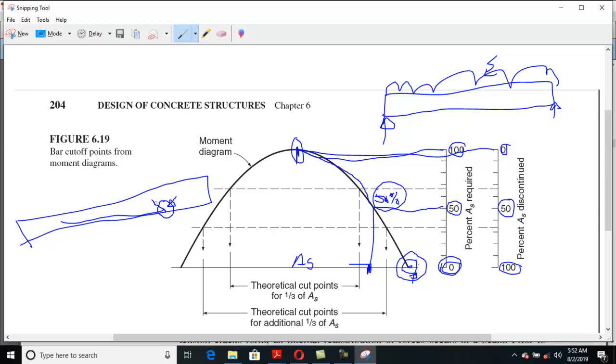Once this crack builds up, the effective cross-section area at this point of the beam is reduced, and so the shear capacity of the section is reduced. So if you want to prevent this kind of shear stress concentration, you need to extend this critical point to the actual point.